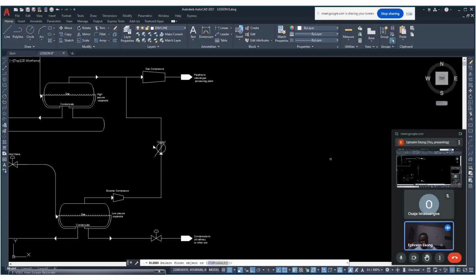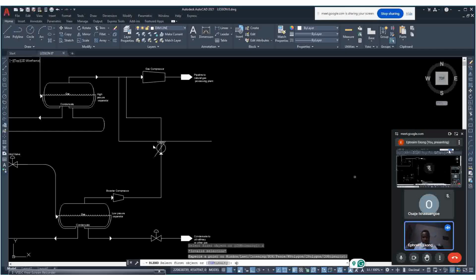Click on, let's again, type out enter, type 300 enter. Going on here. And let's do this. Click online. Let's see this pattern, if it will move. Okay, click on fillets. Type R, enter, 400, enter. Okay, click here and also click here.